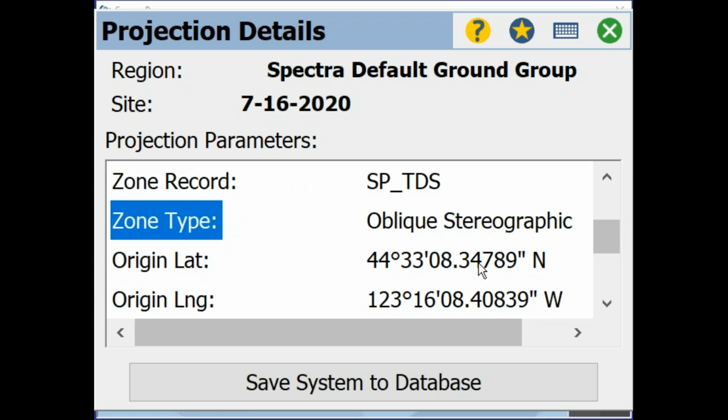That's because when you go into this default mode, you have to have a map projection somewhere. You cannot take latitudes and longitudes on the curved surface of the ellipsoid and draw them on a flat piece of paper without using a map projection somewhere. Again, the only difference between mapping plane mode and default ground mode is that in mapping plane mode, you pick the projection, and in default ground mode, we initialize this default projection.